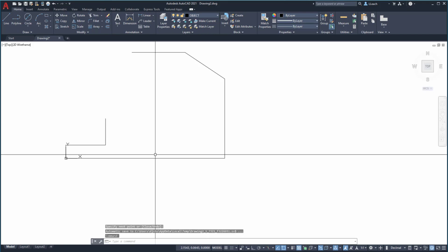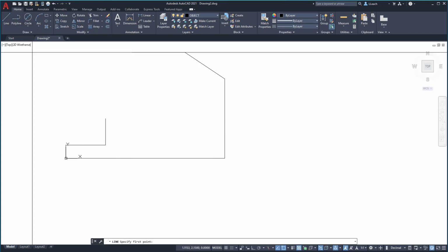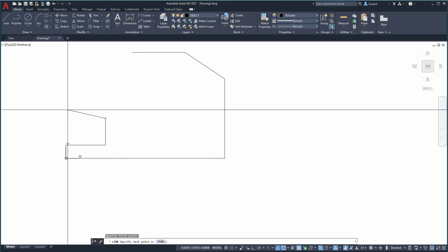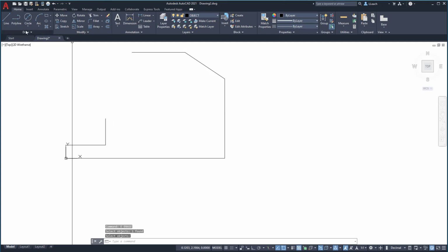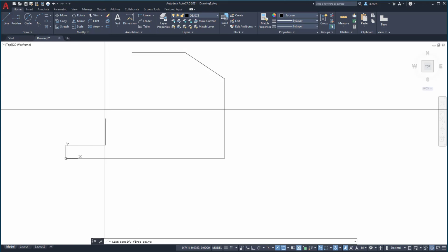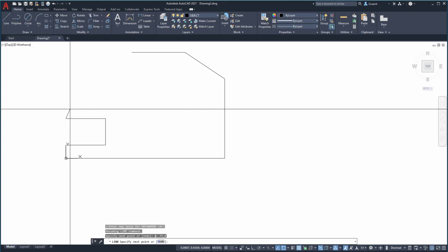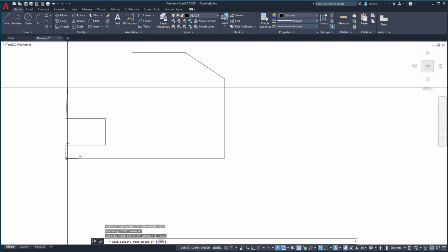And then I accidentally clicked off of that line. Let me start back where I was. I accidentally hit something with my hand. So I'm going to go back to my line from here. I'm going to go @ -0.75, 0. There we go. And then from here, I'm going to go straight up.